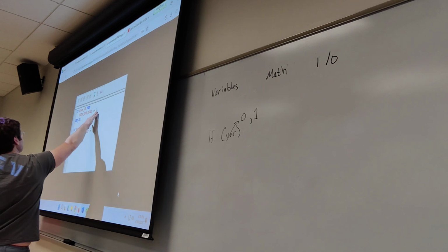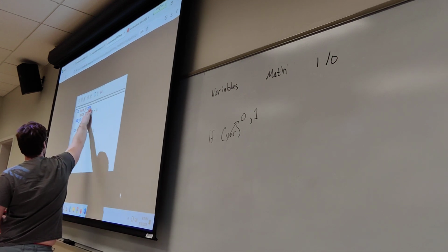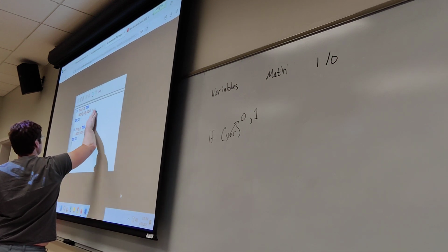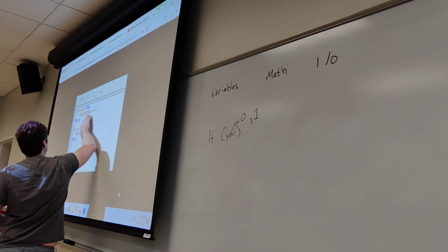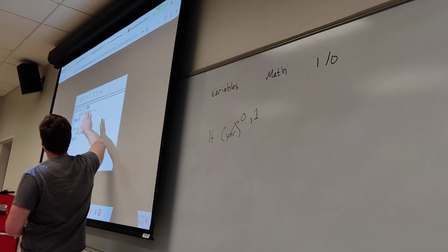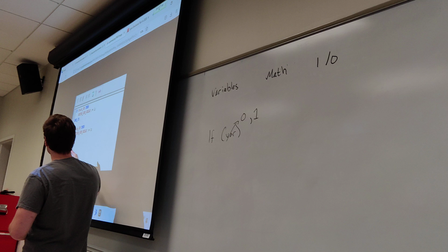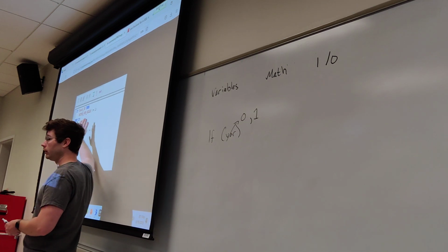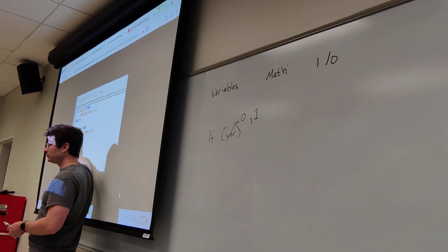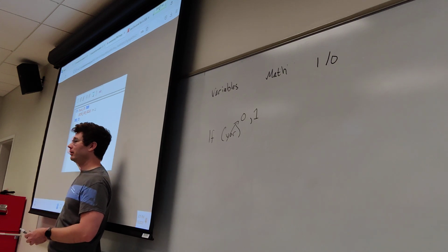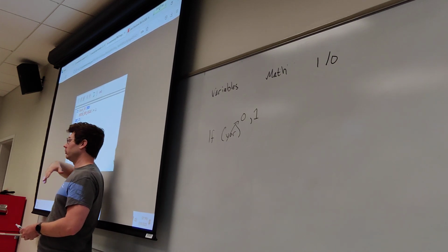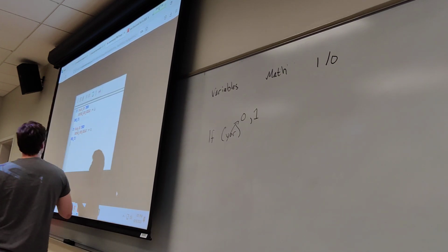Okay, also notice that at the end of these lines, not all of them, for example, these thens are not terminated by semicolons, but these are. Okay, so for example, Arduino also uses this same line ending, okay, where it's terminated with semicolons, and if you don't have a semicolon, you'll get some weird errors and it will complain at you, it won't compile, or it'll have some weird behavior, okay?